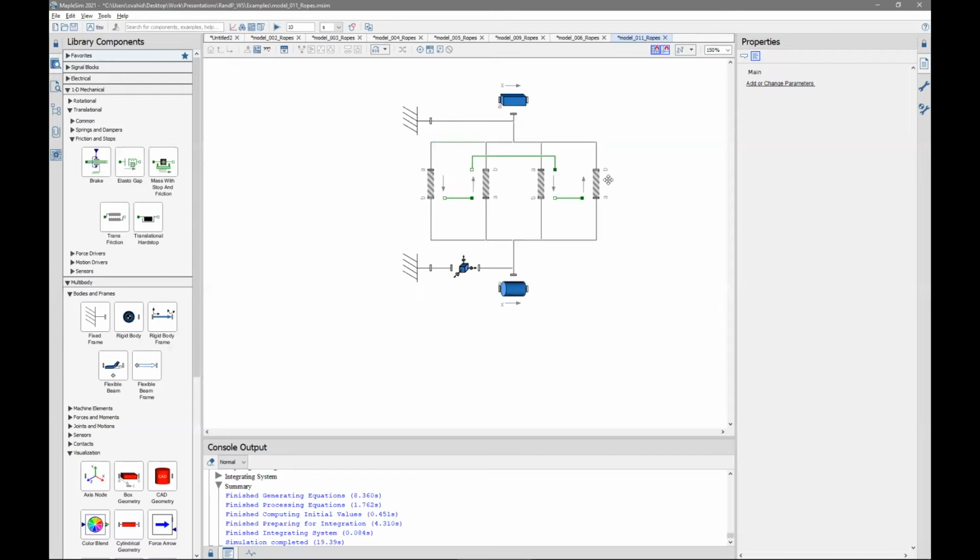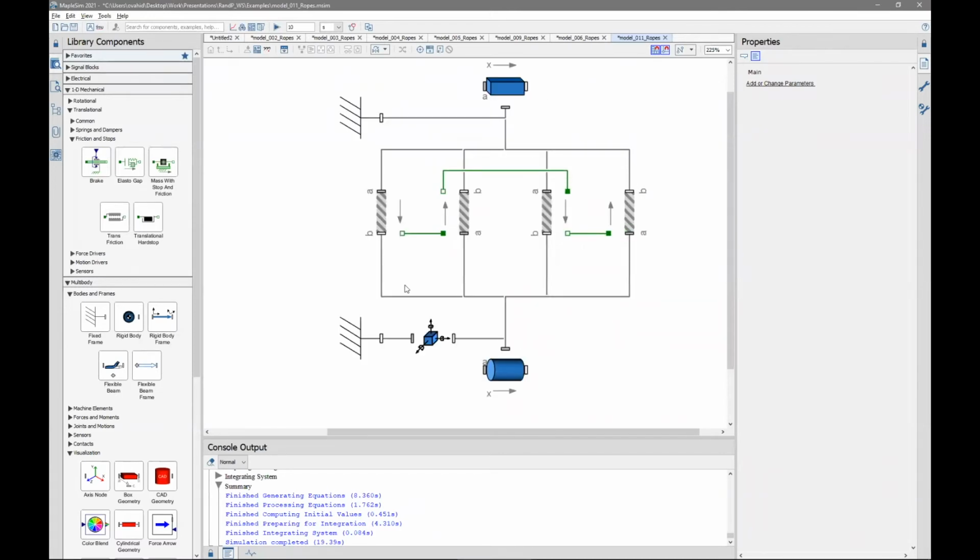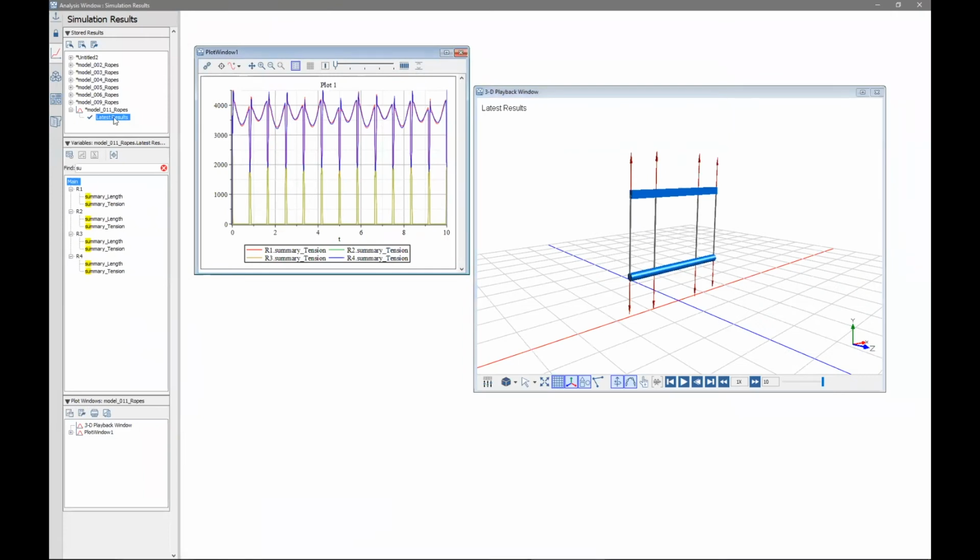So I'm going to zoom in to emphasize another important point. When we have segments like this, where the material is going to exchange between ropes, you have to make sure that the rope arrows that come with the icon point in the same direction, and you don't break this continuity, so that it has the same meaning as where the rope is going. So I'm going to save this result, the bad result, as original.